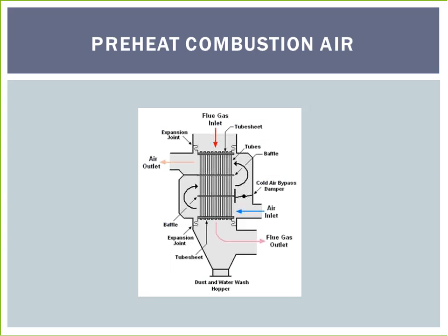If you have a large temperature difference, 20 degrees to 40 degrees, between your boiler intake air location and the ceiling of your boiler room, and this hot air is a result of boiler and stack losses, you can increase your boiler efficiency by either extending the intake upwards or forcing the hot air down. Both options may require a fan and ductwork. If the hot air is due to boiler wall losses, you may want to consider insulating the boiler.